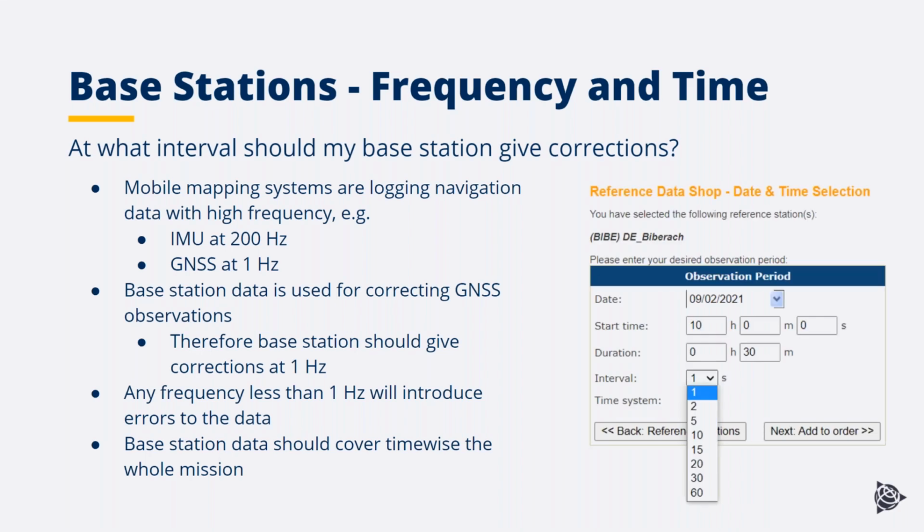If you are familiar with the Trimble reference data shop, there's this menu where, when you order the data, the interval by default is usually 15 seconds. So you have to always remember to change that to 1 second data.